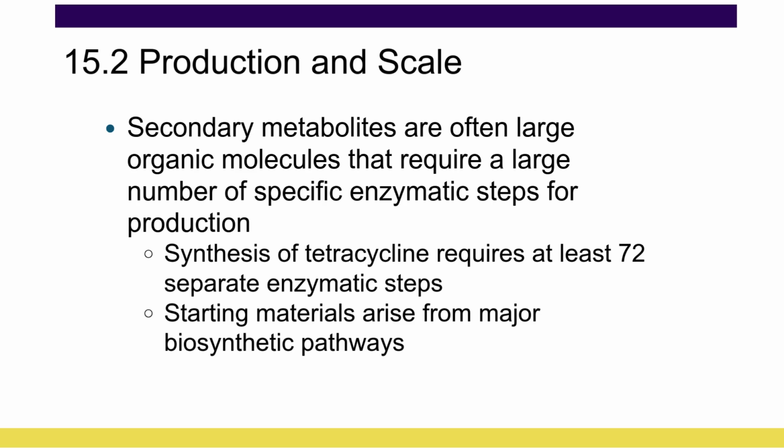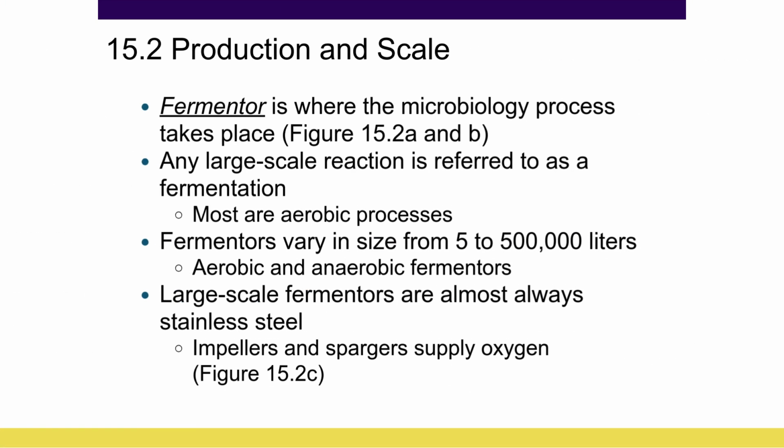Now let's talk about where this happens: the fermenter. The fermenter is the vessel where the microbiological process takes place, as shown in figures 15.2a and b. In industrial microbiology, any large-scale reaction carried out by microbes is referred to as a fermentation, and most of these are aerobic processes requiring oxygen. Fermenters vary enormously in size, from small 5-liter lab units to enormous vessels holding 500,000 liters. There are designs for both aerobic and anaerobic processes.